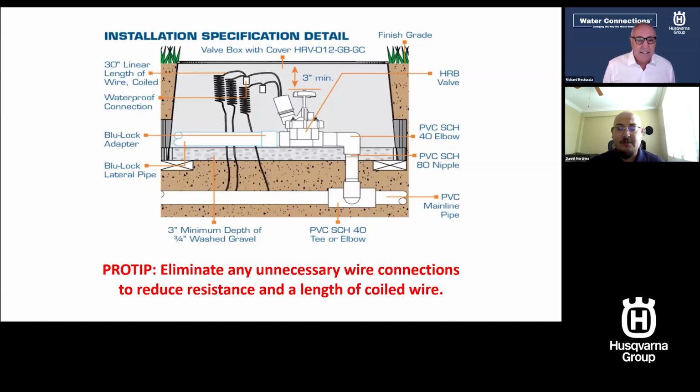But if you have a circuit that's just so close to activating the station, coil up a piece of wire like that. It creates a little magnetic induction, helps pull that current through the wire. It might help you get a station to activate when it wasn't going on. Wow, that's really a good tip. I hadn't thought about that before, but that'll be a troubleshooting time saver for me, Danny. Thank you. You're welcome.